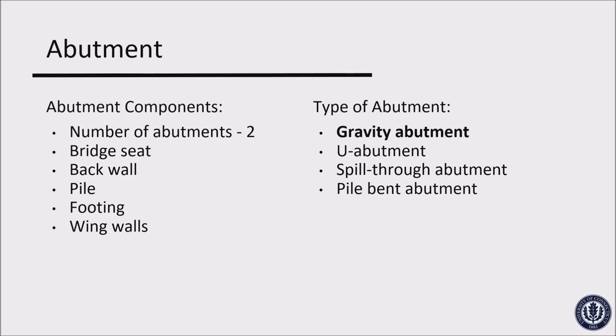Rather than designing a footing ourselves, we decided to design the abutment to rest on top of the existing foundation, as it is adequate to support the bridge. This would avoid the unnecessary cost of digging to install new footings. We also decided the wing walls on the sides of the abutments were not necessary, as the embankment is directly behind the bridge. Considering which abutment components we needed and which we didn't, a basic gravity abutment fit our need the best.